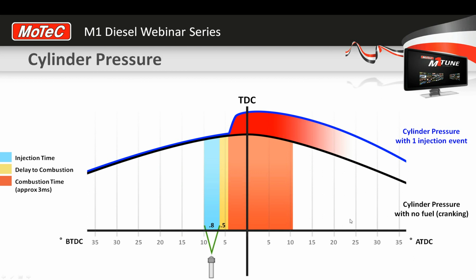And so that's represented here. We have a blue line showing that pressure increase, and this is a sharper than normal pressure increase, certainly compared to a petrol engine. So we get all the fuel burning off very quickly, so we get a very sharp pressure rise here, and that sharp pressure rise is the diesel knocking noise that you can hear on an older style diesel.